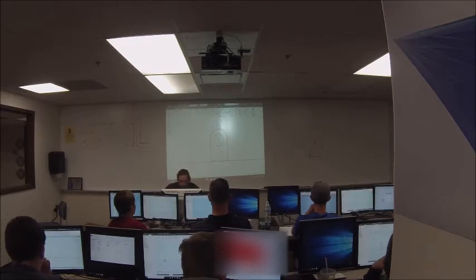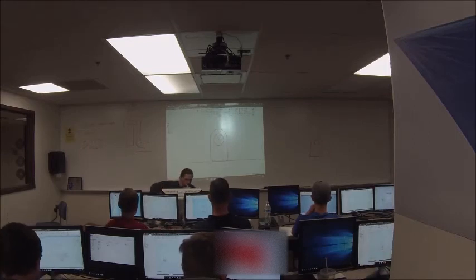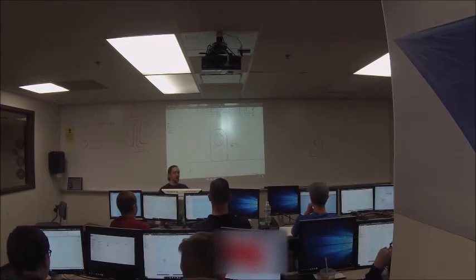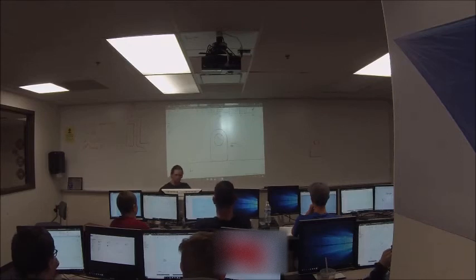There's one other thing that's extremely powerful in Inventor. Well, there's two things actually. We're gonna go over these very briefly and then move on. All right, if you go into the edit constraint dialog, you can do math in these. You can just type in equations in these boxes and Inventor will figure it out. And when I say that it can do it, use it. Don't sit there with a calculator calculating what dimensions you need when you can just type the calculation in the box.